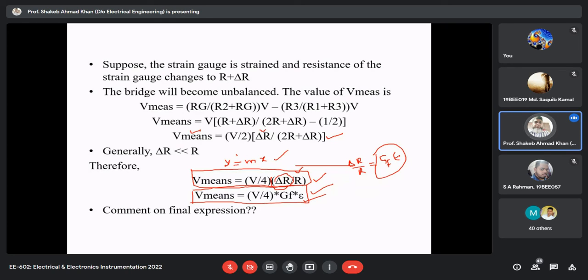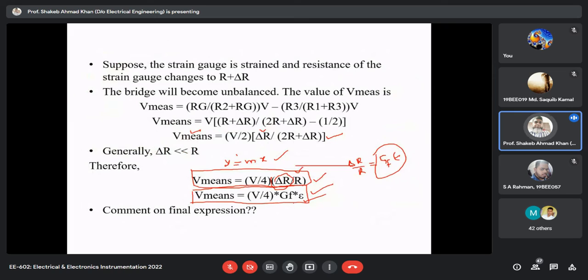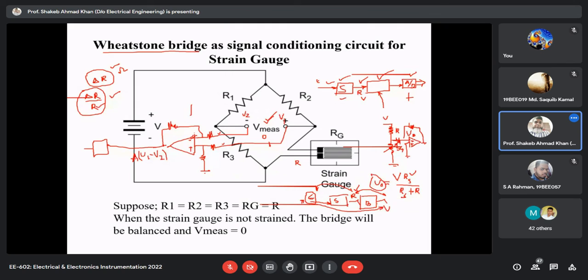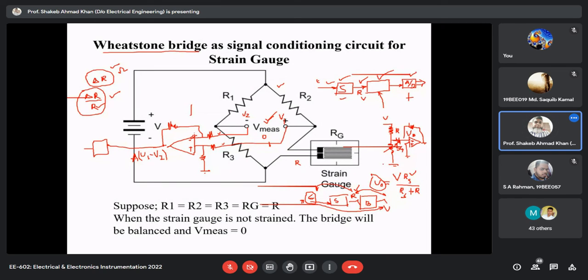This is why the linear relationship is required. That is not in your course, but it helps tremendously in calibration. So this Wheatstone bridge circuit by default provides the linear relationship between the stimulus and the output, whether intermediate or final. You can see with the strain also it is linear. This is how this circuit is considered best in comparison to other circuits. Here I had shown you one of the primitive, simplest circuits, called the voltage divider. If anybody has any question regarding whatever we have discussed, you can ask, please.